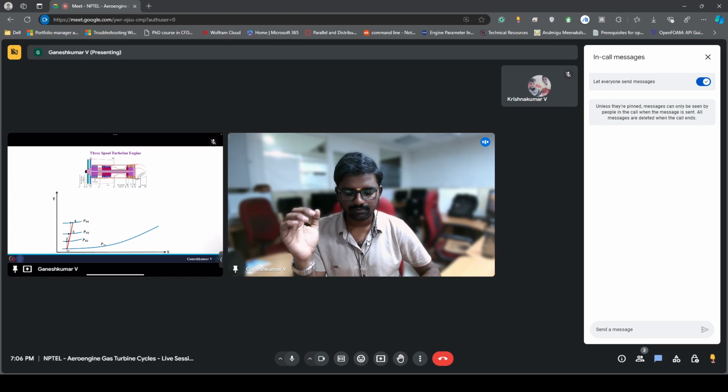So in the core stream you have the intermediate pressure compressor, which is between 3 and 4, and then comes the high pressure compressor, where you will reach P5. Then you have the combustion chamber where you are adding heat, and so you will have the highest temperature T6. So T06 would be the highest temperature, and that will be the turbine entry temperature at this stage.